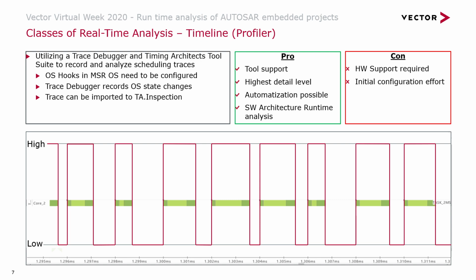Now, when you talk about these timing requirements, what do we actually mean by that? What can you do with it? Let's say for periodic tasks, I can take the configuration of the periodic task and derive which period is the one I want to have. And then I can check it on basis of a requirement, so that I can check it from activate to activate and always get the period between that. Or, for example, I want to make sure that the overall runtime of this task doesn't exceed the period, or doesn't exceed 80% of the period, for example. So these are quite generic things, but you can also work project specifically.